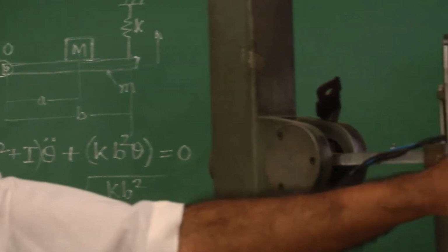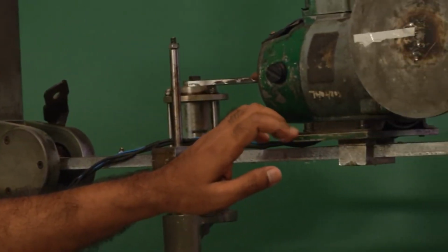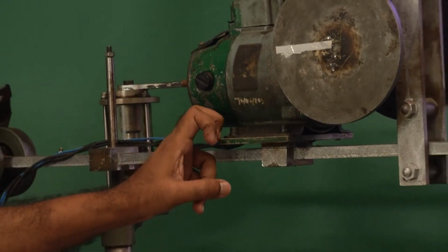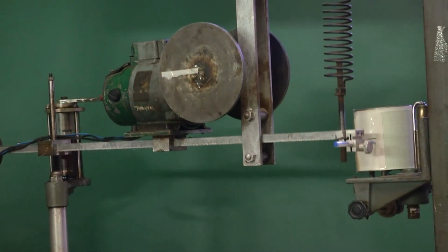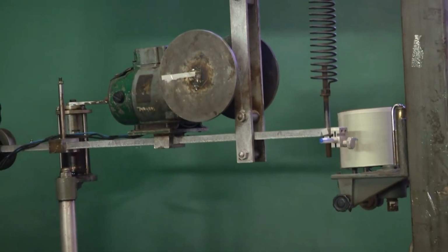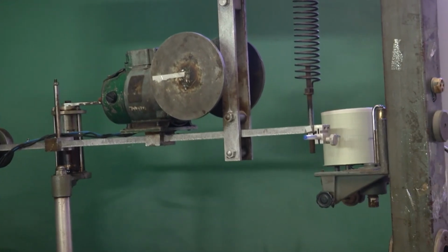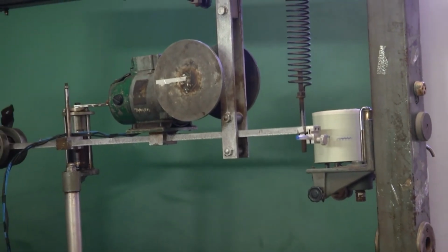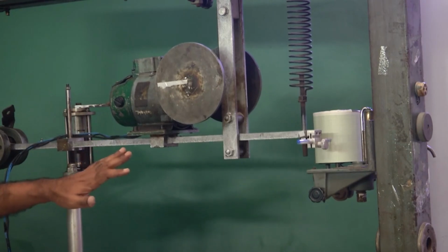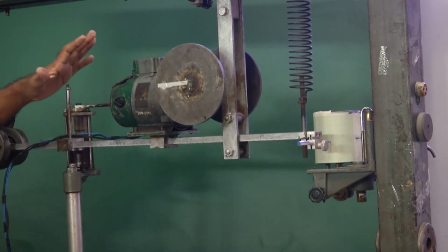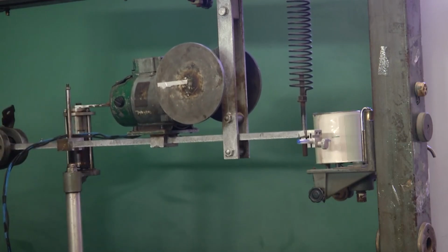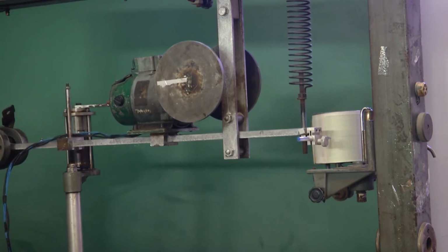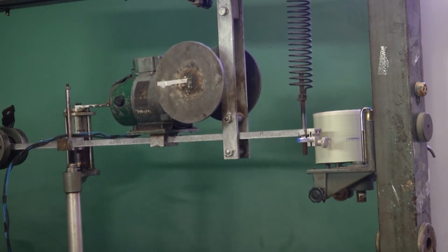Experimentally, how do I find the natural frequency? Now, you can see that if I perturb it, just like we discussed in the first topic, I give an initial displacement and then release it. So, x naught is given some value, and v naught, the initial velocity, is 0 at time t equal to 0. Once we give that initial disturbance and release it, the whole system vibrates naturally at its period of oscillation. So, the free vibration natural frequency is what we observe here happening.